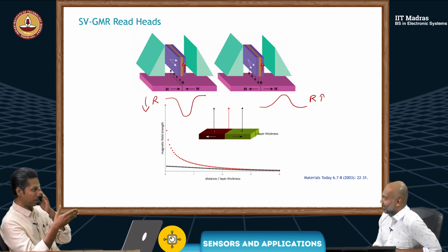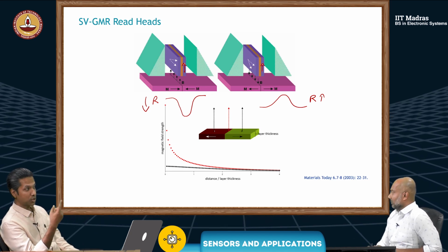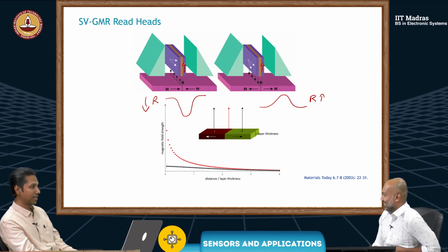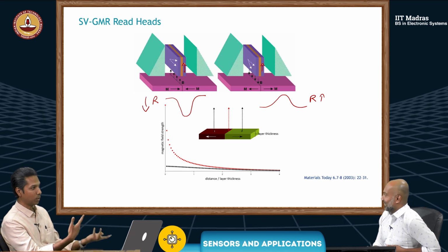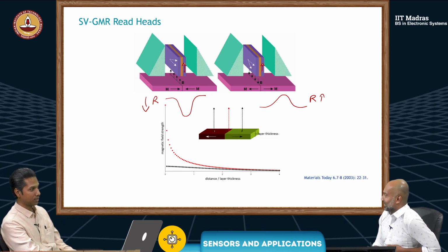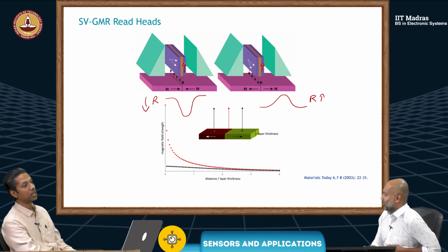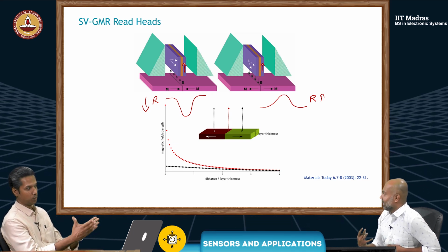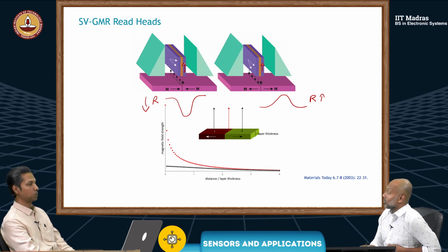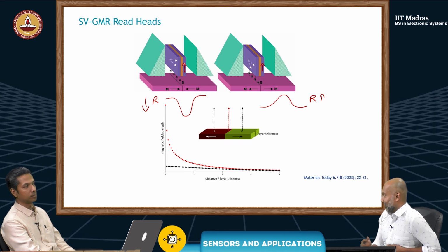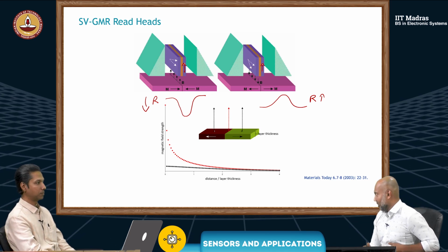Also, the speed at which I can read. The search coil that you discussed had some bandwidth, decided by its parasitic capacitance, coil inductance, and so on. But here the bandwidth is very high, which means you can read very quickly. So it's faster, and there you have small size, and you can also densely pack more information into a given area. But it has its challenges, right?